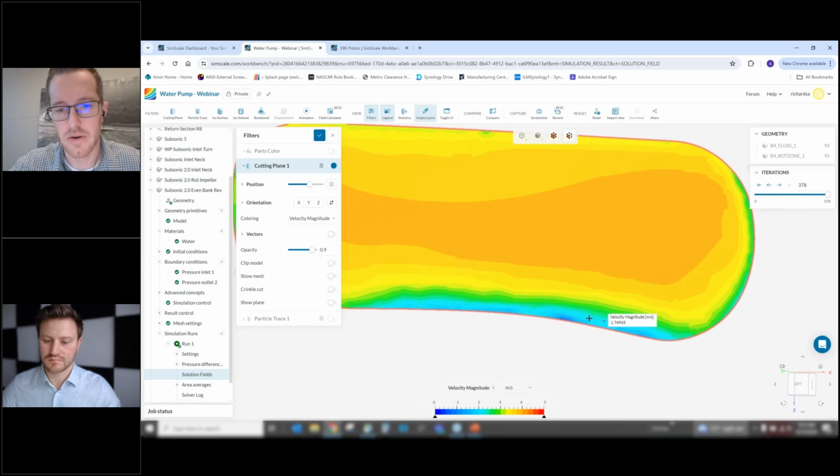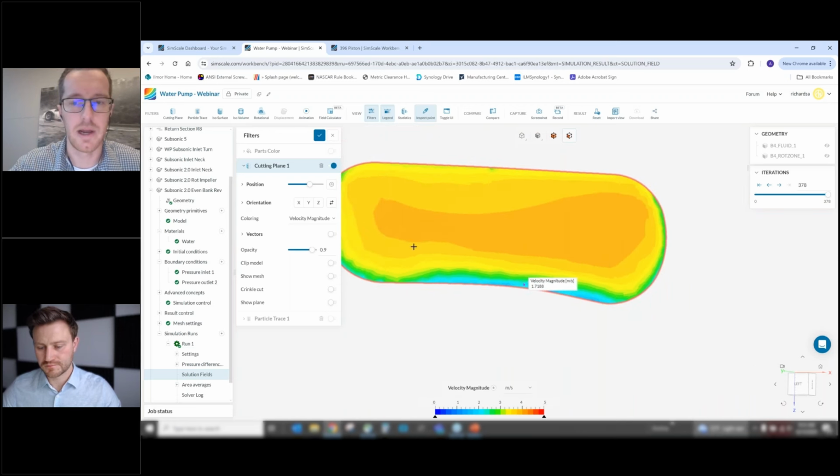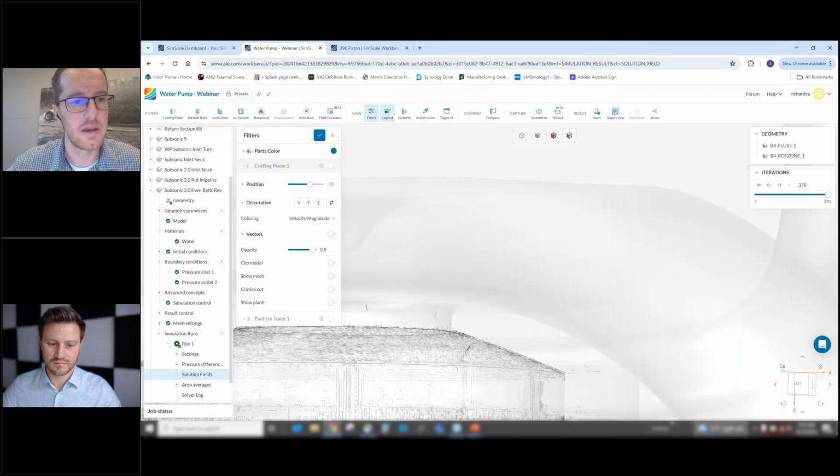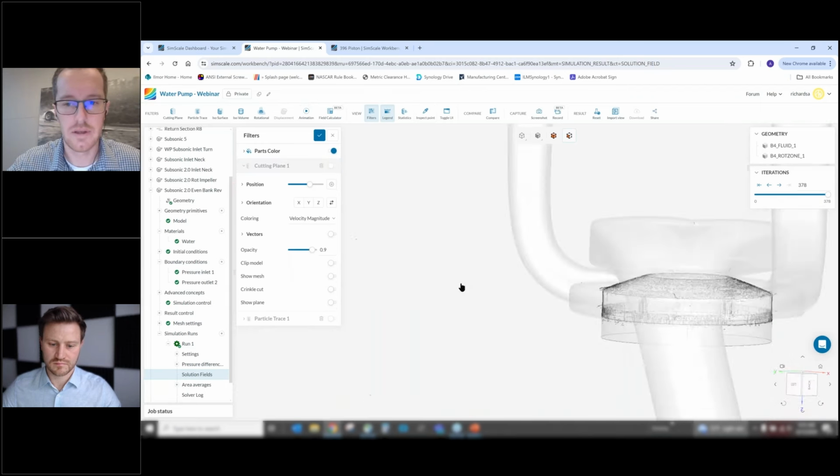And you can see here we've only got just a small section where our flow is diminished, but in general the bulk fluid flow is occupying this entire volume, which is what we're after, and that results in a greatly improved inlet to the impeller. And an improved inlet to the impeller results in an improved net output or net flow for the pump. So that's the final revision over here, and we'll show a quick particle trace.